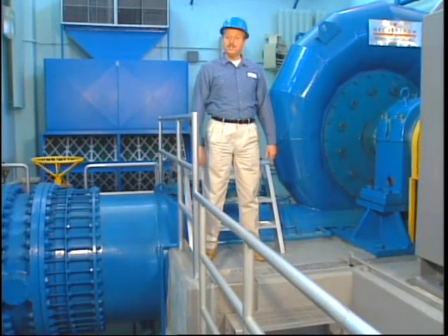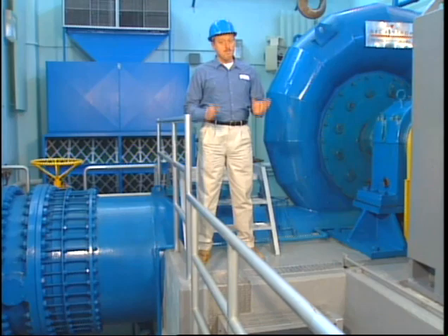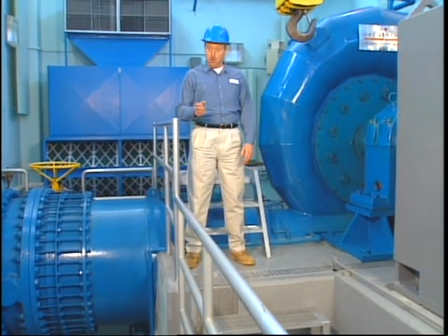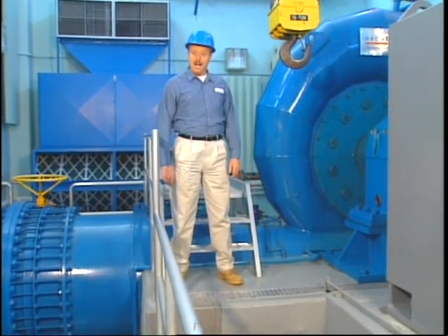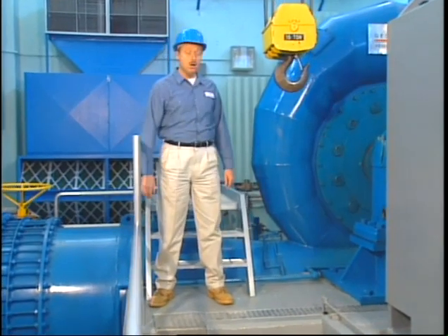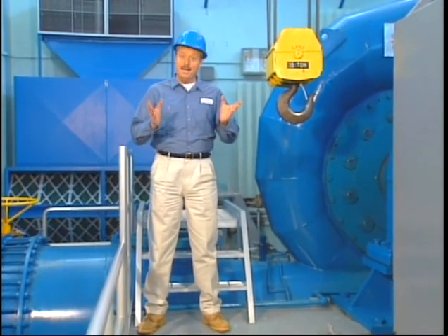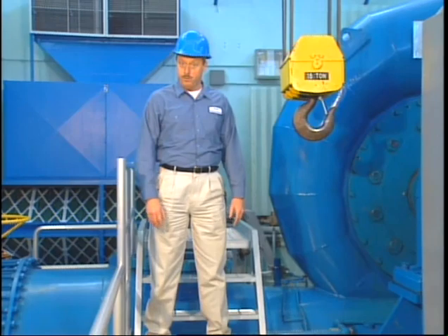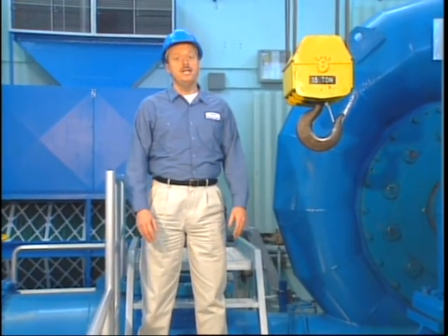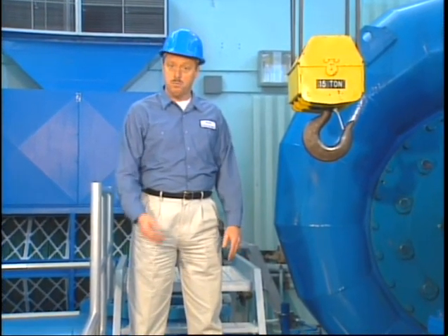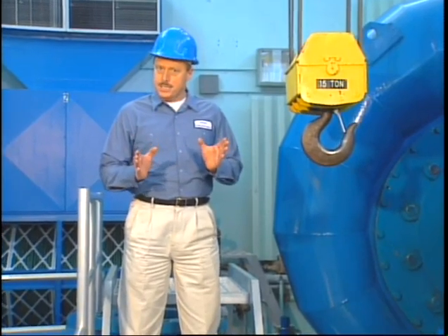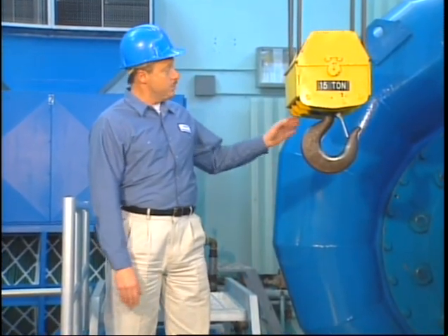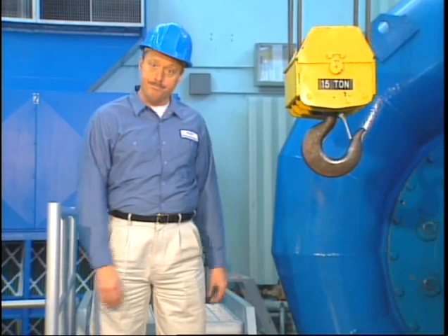And that's a good place to start, knowing what the maximum load is for the piece of equipment you're working with. The rated load capacity of a crane should be clearly marked on the side of the machine and in the manufacturer's operating manual. Of course, that also means you need to know how much the load is you're transporting. Don't just guess at this. An overloaded crane is a disaster waiting to happen.